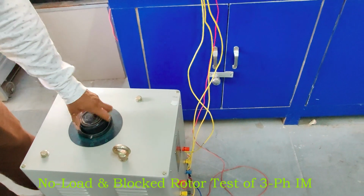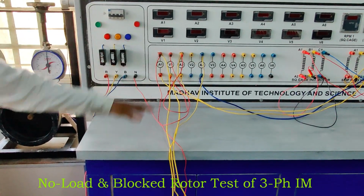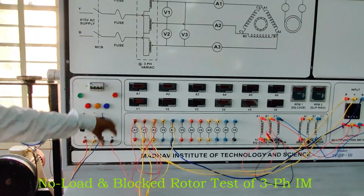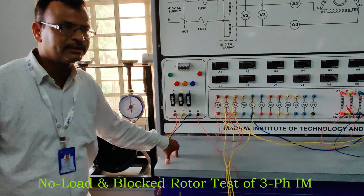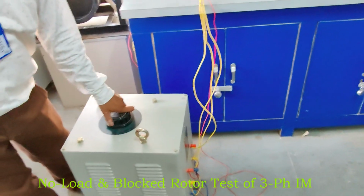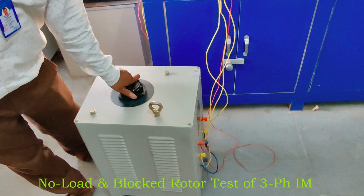Otherwise, if the connection is wrong, high voltage will go into the machine and the meters and voltmeter may be damaged. This is the main precaution when you perform any electrical engineering experiment with an auto transformer.